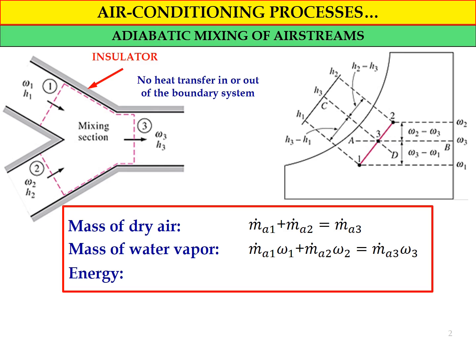If you implement the energy balance equation, we get E mass in equals E mass out, because now we have two inlets and one outlet, so E mass in at inlet number 1 plus E mass in at inlet number 2 equals E mass out at outlet state number 3. In terms of the equation, we have ma1 dot multiplied by h1 plus ma2 dot multiplied by h2 equals ma3 dot multiplied by h3.